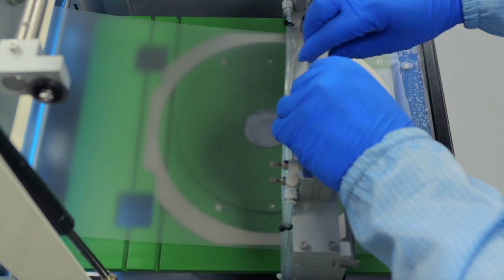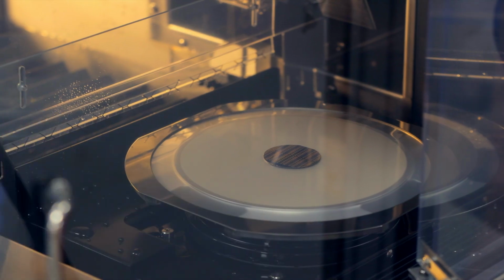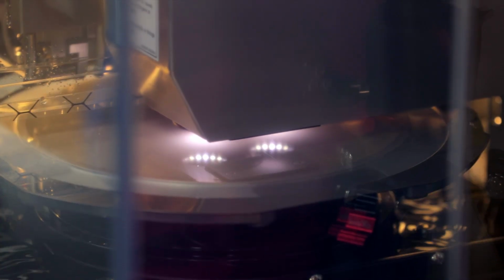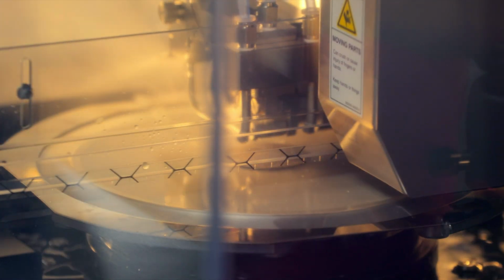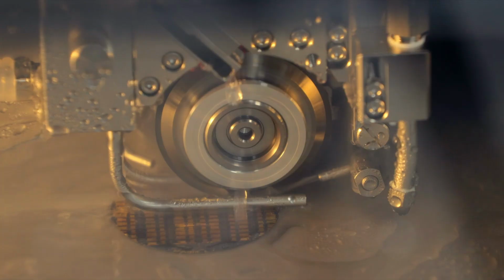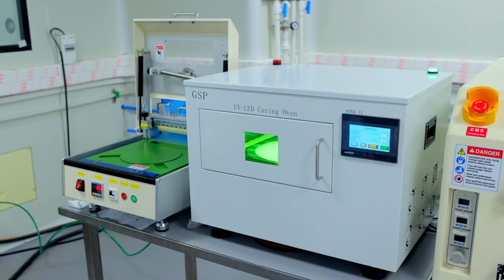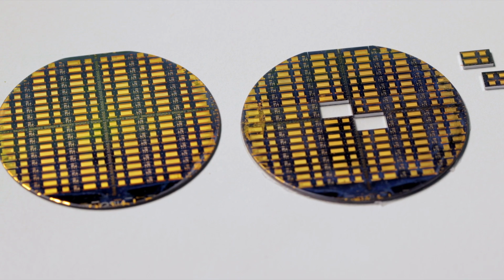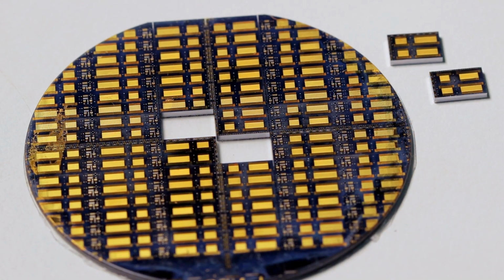The wafer we have just processed is divided into squares, along which we will now cut using a diamond blade to realize what are called dies. Each die has the devices or circuits we just realized using our 10 mask process.